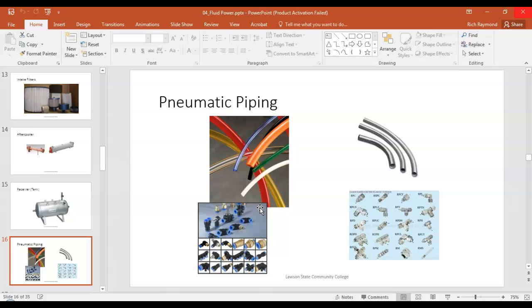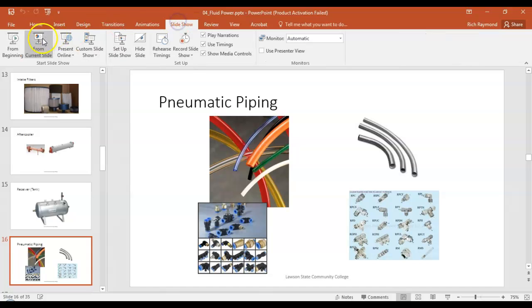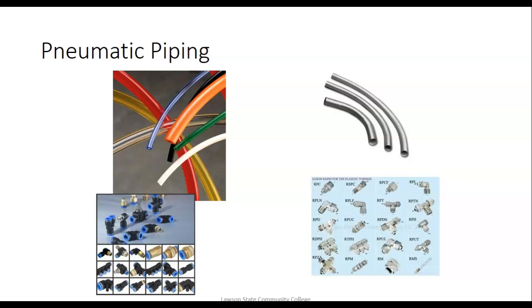So what's the advantage of high pressure? What's the big advantage of high pressure over low pressure? Well, technically, no. But I think you got the right idea. When we come up here and generate a force, that's how much work we can actually do, how much motion we can actually cause. Force is equal to the amount of area you're applying the pressure to times the pressure itself.